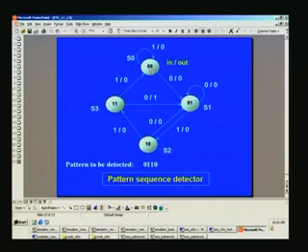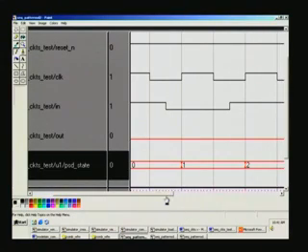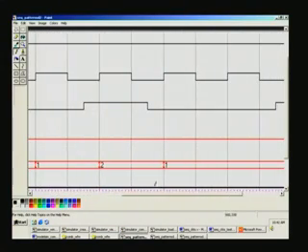Let us see that. We are in S0 state, yes. If it is 0, it should go to the S1 state, right. If it is 1 only, it will remain there. So, it is here. So, is that all right? Okay. So, where are we now? In 2, right, at this state. So, at this state what counts is not this one, but this 0 prior to the positive edge clock transition, right. So, at this point of time only this input is taken and processed, and this corresponds to this state, and as a result of which you get a new state here. And let us see that in state 2, when input is 0, it should go to S1.